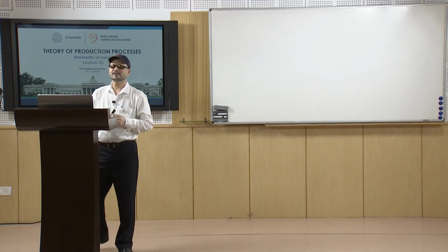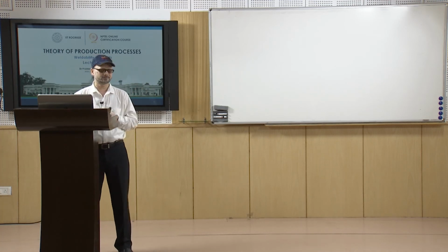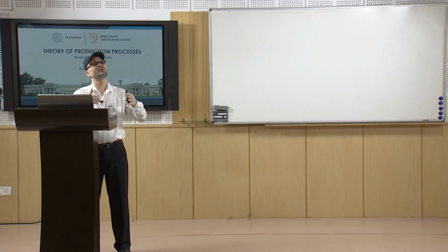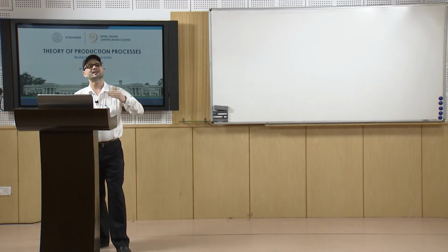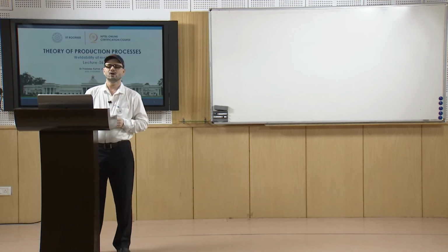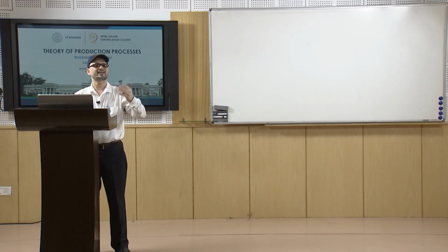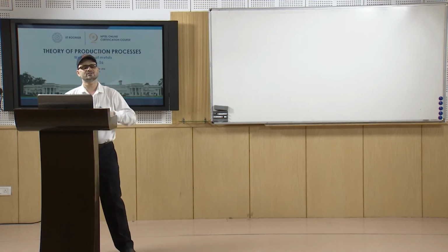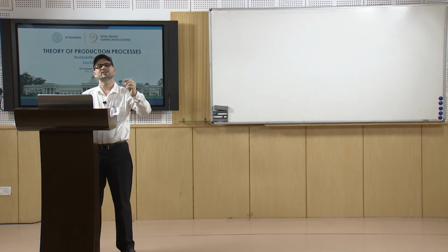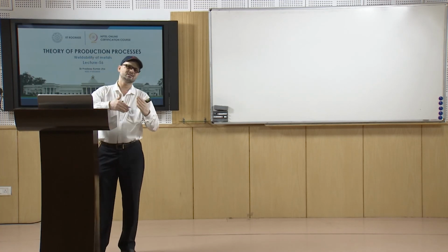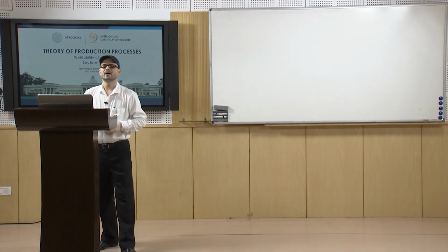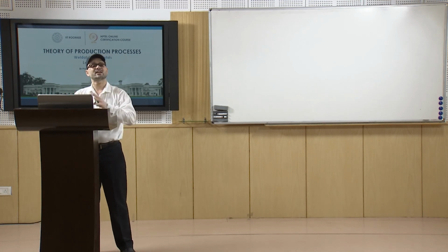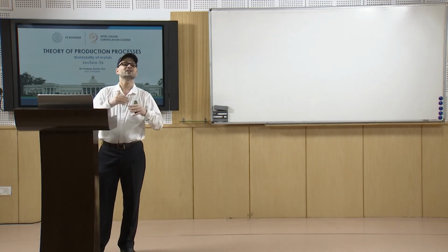Basically, for that test you normally have two types of test. One is the fabrication weldability test. In that we do the hot cracking test or cold cracking test, or the hydrogen induced cracking test or root cracking test, all those tests are carried out. Similarly, you have the service weldability tests. That service weldability test includes properties like tensile, hardness, then impact test and fatigue, corrosion, all that type of test can be done, and you can talk about the weldability issues.